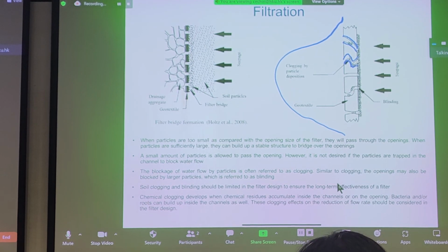Now, let's say this was a PVD drain and you let some particles arch in front of a channel, for example here, you can block it off. Another way is if you let particles accumulate inside the filter, this can also block it off. So these are the two main mechanisms for blocking off the filter, and that's also why we get well resistance in PVD drains.